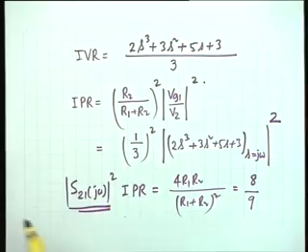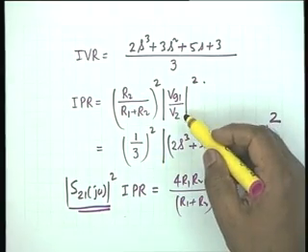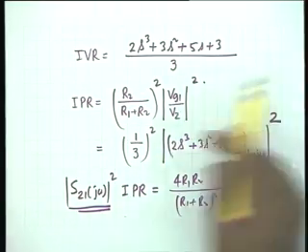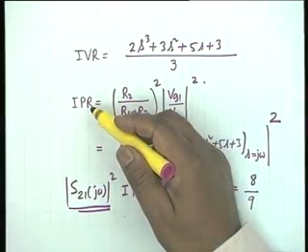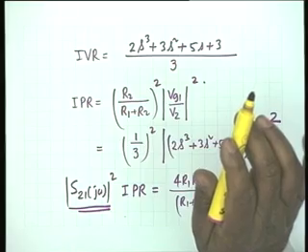In the few minutes that are left, is there any question? We are not going to come back to scattering parameters again. So why have we divided the mod term by 3? Mod term by 3 because it is Vg1 by V2. This is not insertion voltage ratio. This is simply the reciprocal of V2 by Vg1. It has nothing to do with the insertion voltage ratio. IPR is not in terms of IVR. Okay, that is the reason. Any other question?